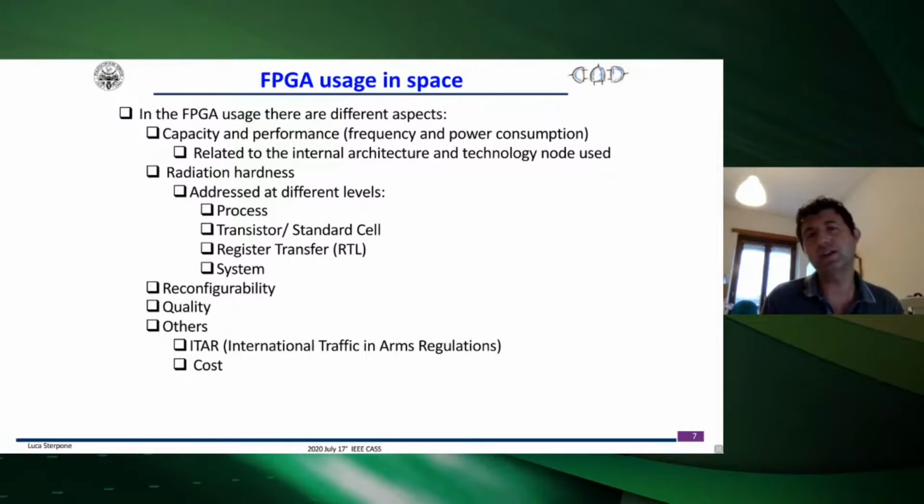Of course, a satellite can have shielding to protect. Generally, this is something like aluminum shielding to reduce the impact of the particle. But some of the particles have high energy and then traverse the shielding and reach the electronics. So here we are talking about FPGA in particular.